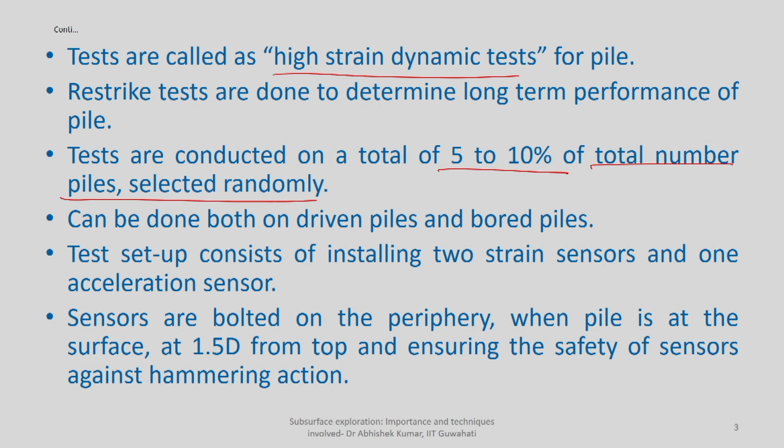Similarly, you can do the test both in driven piles as well as in bored piles. In cast in situ piles you cannot do the test because there will not be any kind of hammer impact there. The test setup, as I mentioned, the beauty of this test is you need not go for any external source of loading because anyway you will be driving the pile into the soil. So, hammer impact will be there.